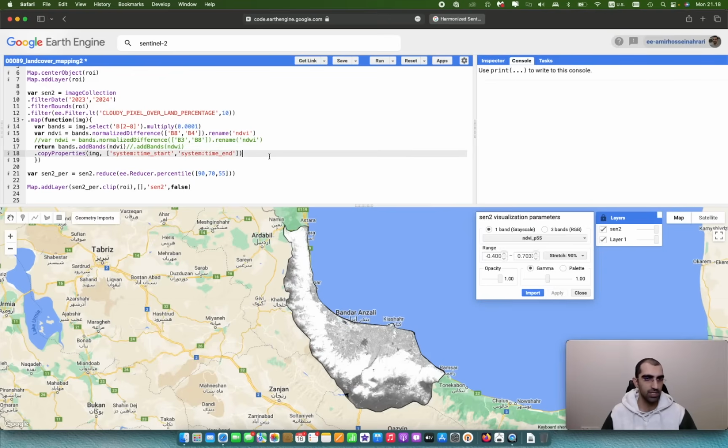And then you can also reduce the number of percentiles. As I said, it is totally up to you. You can have only 75 and 55%, or you can have multiple percentile values. It also depends on the accuracy of the output. If the accuracy of the output was not good enough, then you can add an extra percentile value. Here I want to limit it to 2 percentiles, 75 and 55.